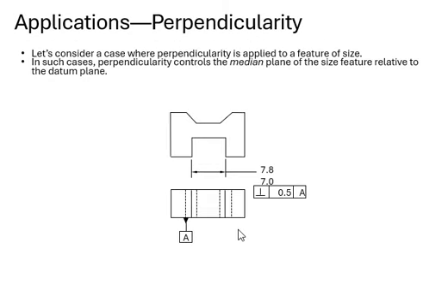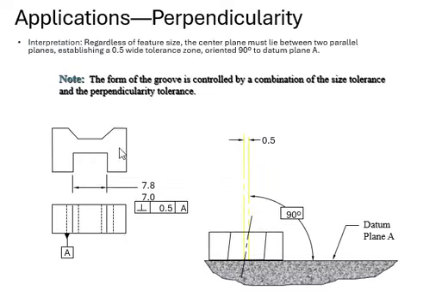All right. Then you give it another part, and right now we're going to measure the perpendicularity by using a different feature. Here we're going to use the axis of that, and our plane is identified with this surface gauge. So right here is our axis, and your angle has got to be 90 with this datum plane.